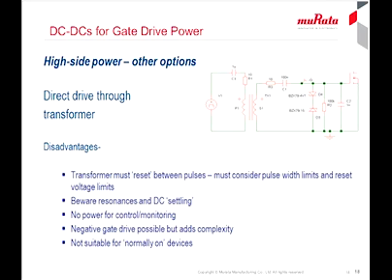If the load is shorted, other protection circuitry may operate, reducing the duty cycle to near zero, but then there is little power available from the gate drive PWM signal, and the voltages may therefore drop out of specification, leading to overdissipation or failure in the power switches. Positive and negative gate voltages can be generated, but with extra circuit complexity.